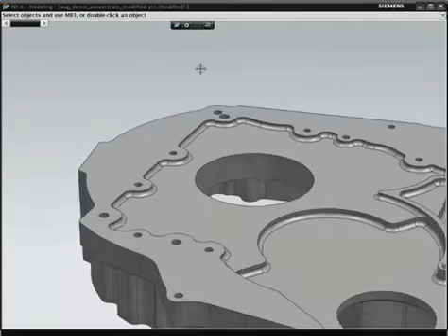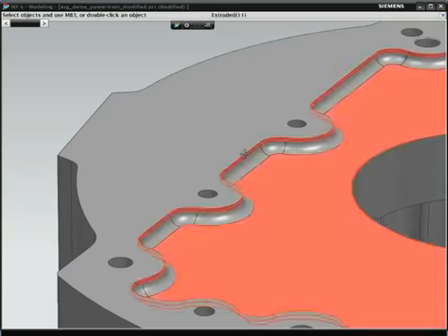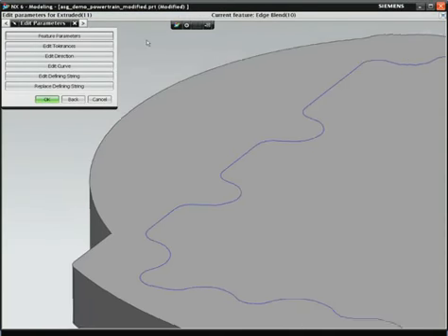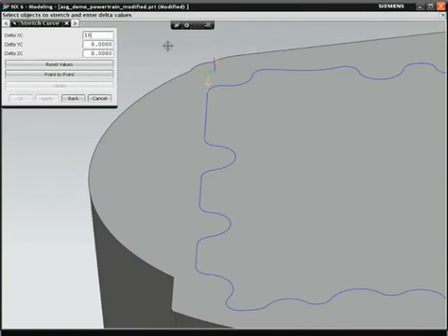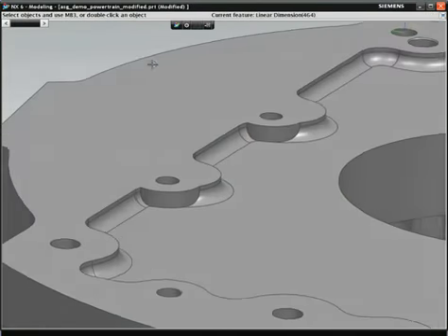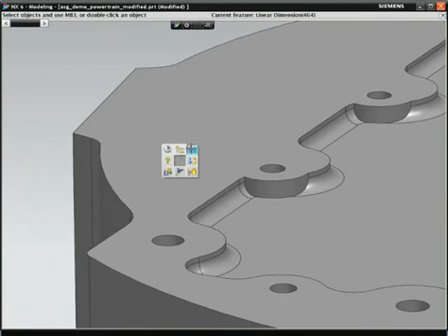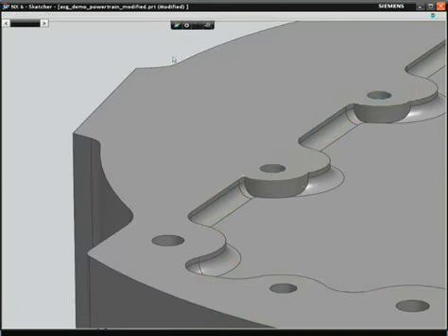The second change requires moving these 2 mounting bosses and holes 10 millimeters. They have been created as part of an extruded profile, which is not a sketch. This is not a problem, as you could stretch the profile to accommodate the change. On update, you can see the bosses are made up of more than one extruded feature, so we now need to further understand the feature history.